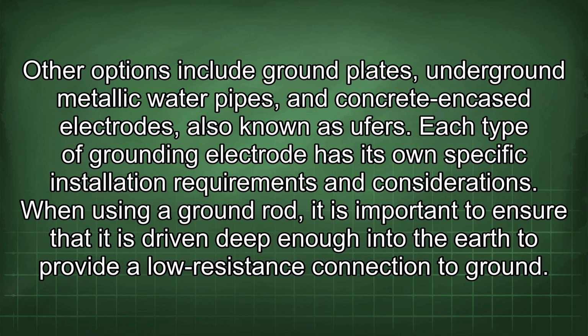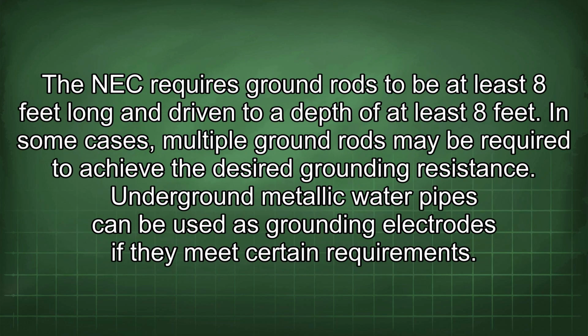When using a ground rod, it is important to ensure that it is driven deep enough into the earth to provide a low resistance connection to ground. The NEC requires ground rods to be at least 8 feet long and driven to a depth of at least 8 feet. In some cases, multiple ground rods may be required to achieve the desired grounding resistance.